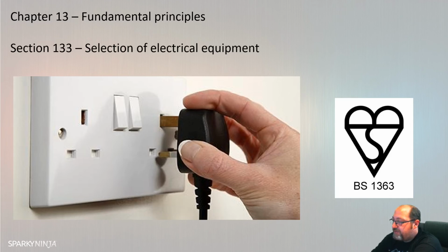It then mentions underneath, if it is done, it needs to be recorded on the electrical installation certificate specified in part 6. So yeah, that's the departure. With regards to electrical equipment, we need to know the characteristics. The voltage of the equipment needs to be suitable for the system. The current, the frequency, power. Equipment which is selected on the basis of its power shall be suitable for the duty demanded of the equipment, taking into account the load factor and the normal service conditions, so the expected demand of the piece of equipment.